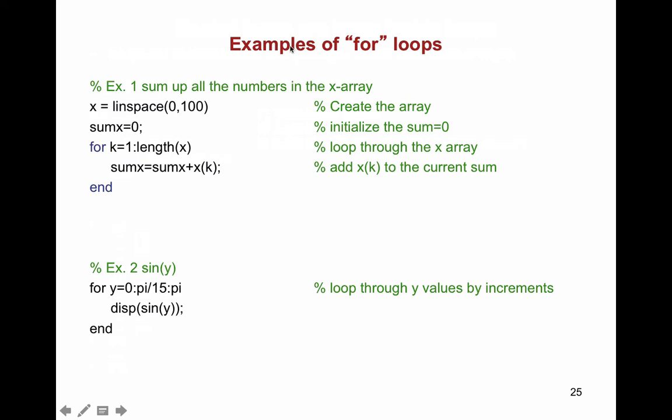You can, by the way, run only this section. Here there's a run section. So I highlighted this section and I'm going to run it. Whoa. I have an invalid statement in here. And if you notice, I wasn't paying attention, but there was a red line underneath here. That's MATLAB telling you that you have a problem here. It says invalid syntax, possibly parentheses missing. Not possibly, certainly.